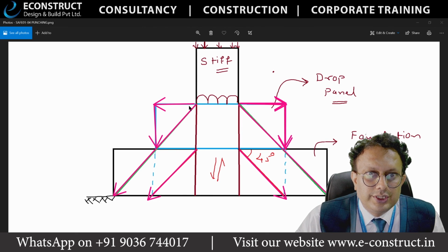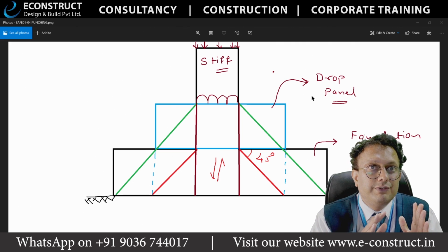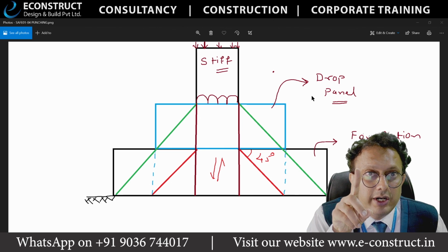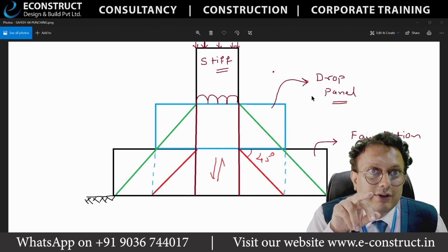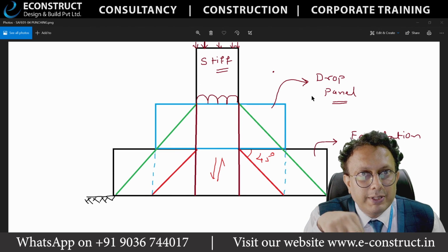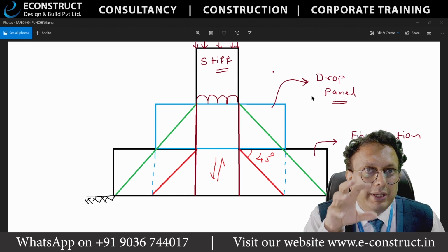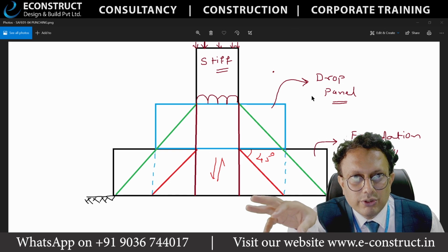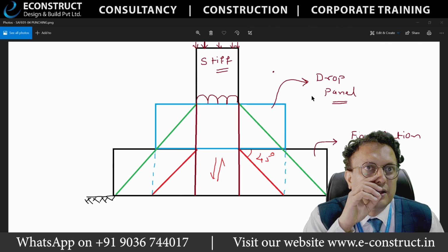Yes. So this is basically used for punching. There are certain types of reinforcement which are punching governing, shear governing reinforcement, that is point number 1, and there are certain reinforcements which are bending governing reinforcement. Sometimes it is punching plus bending, but many times it is either punching only or bending only.